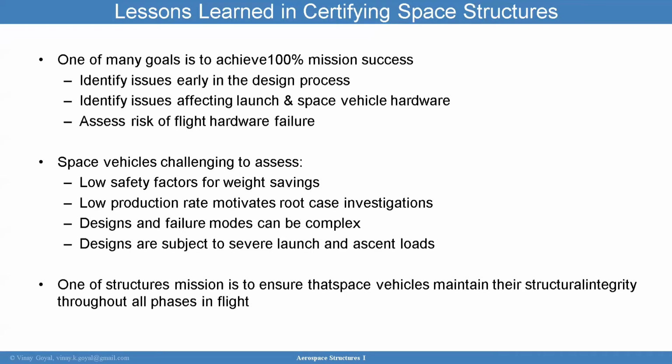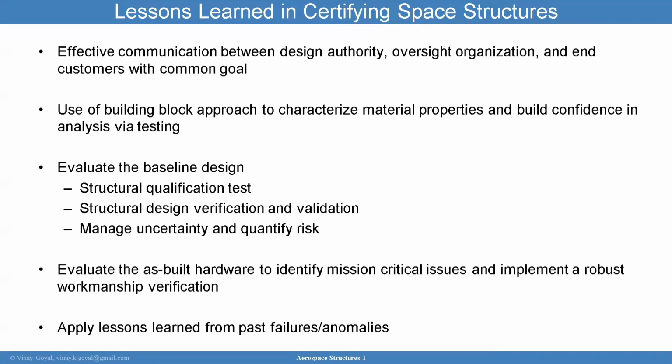And designs really are subject to very severe launch and ascent loads. So you want to make sure your structure can survive through all the phases of flight and that it maintains its integrity as you go through. But to achieve that, it really requires a lot of other things, ensuring that you have effective communication between the design authority and the oversight organization, and that you have the customer goals in mind. So we ought to use a building block approach when you can to characterize the properties and build confidence in analysis via testing.